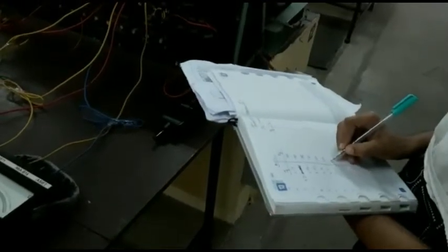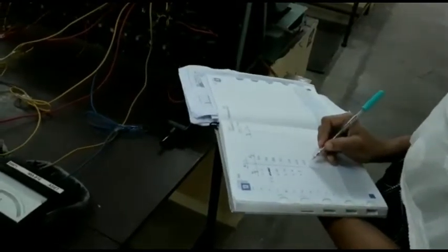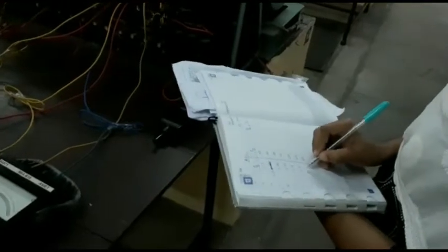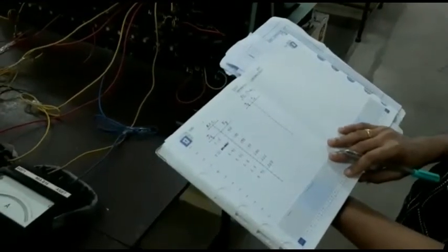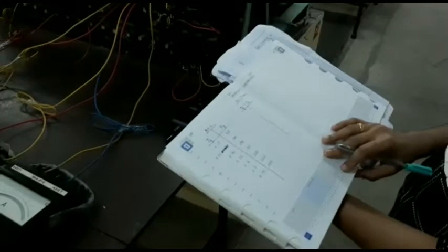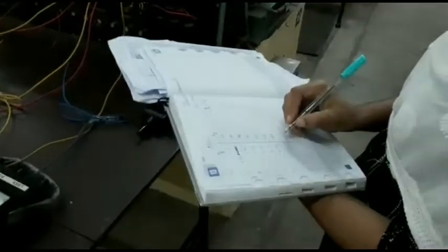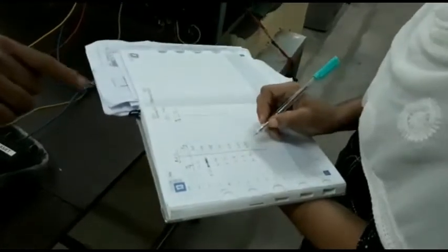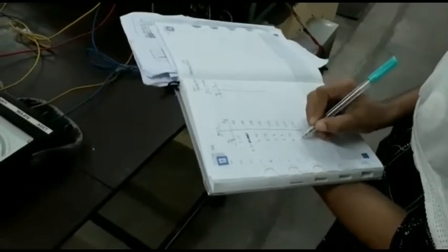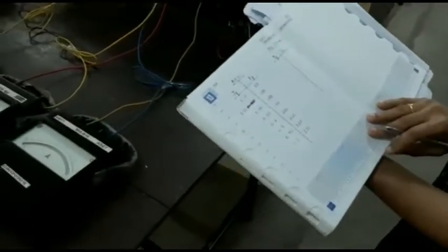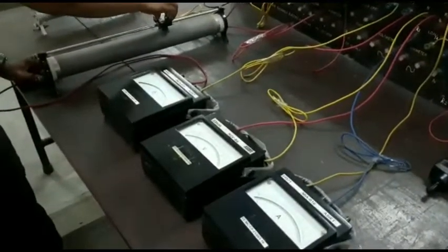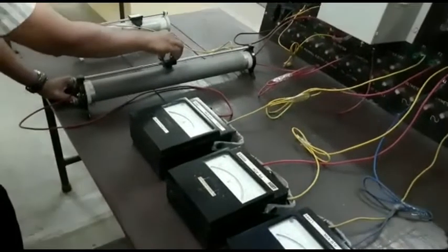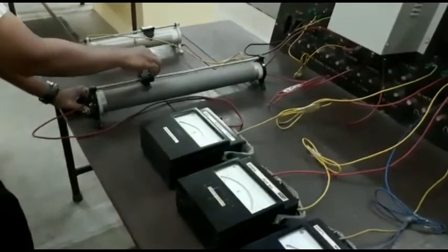You can see that step by step the rheostat is varied and the voltage EG and IF are noted down. For 0.95 you have a generated voltage of 250 volts. Now the final reading should be 125% of the rated voltage. You can record it as 275 volts, the last reading. It's 1.1. Now you have to reduce IF to the initial value of 0 ampere, so you bring the rheostat back to the initial position.